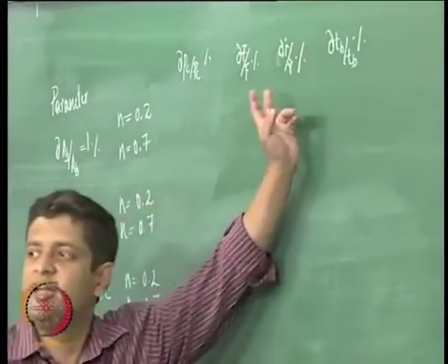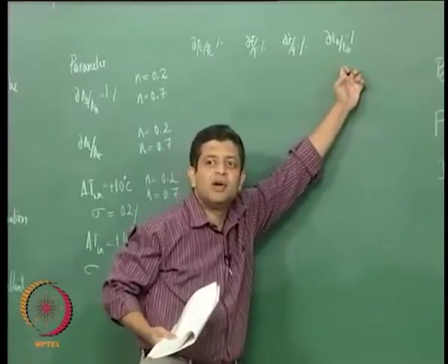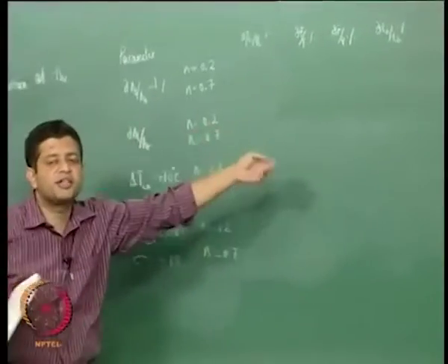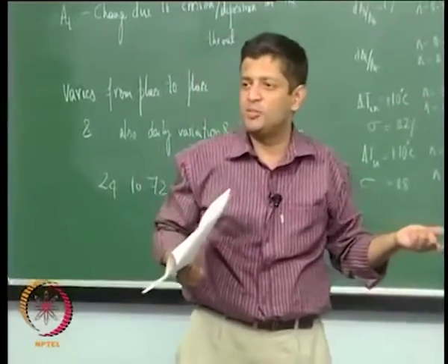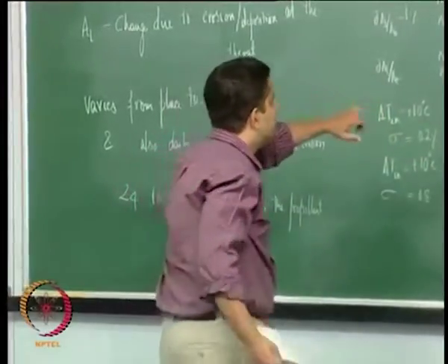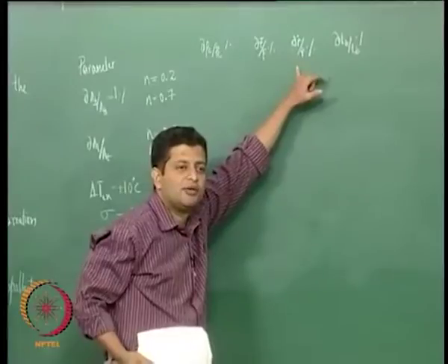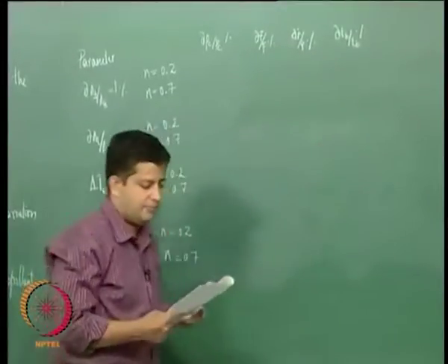This is the incremental change in burn rate and correspondingly the incremental change in the burn time. We know that changes in pressure and burn rate are related: r dot is equal to a P_c to the power of n. So, we can use that to calculate this, and if you know the burn rate, you can also calculate the burn time.